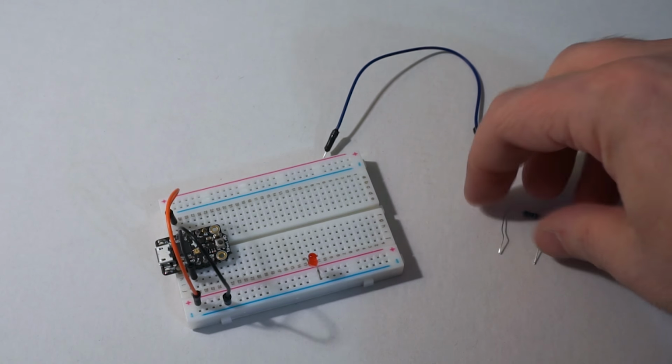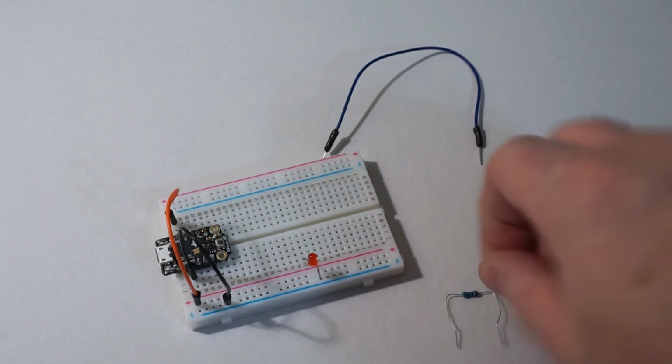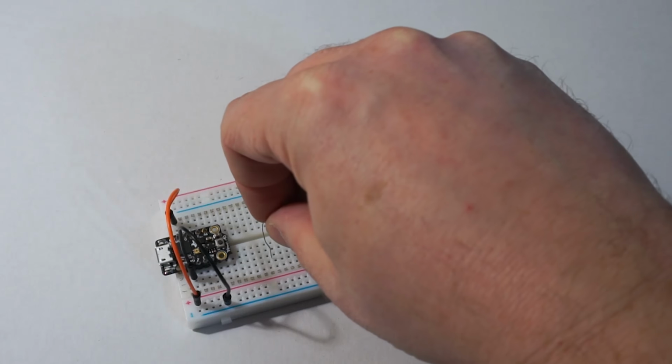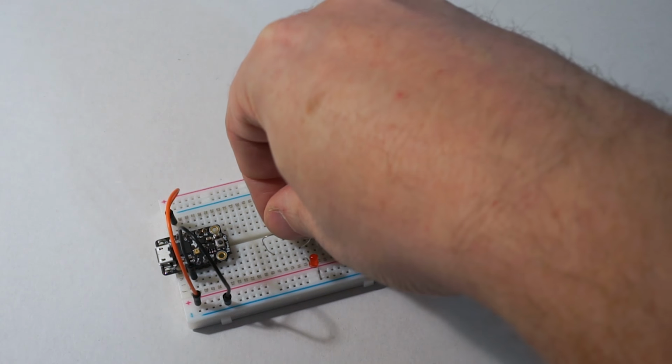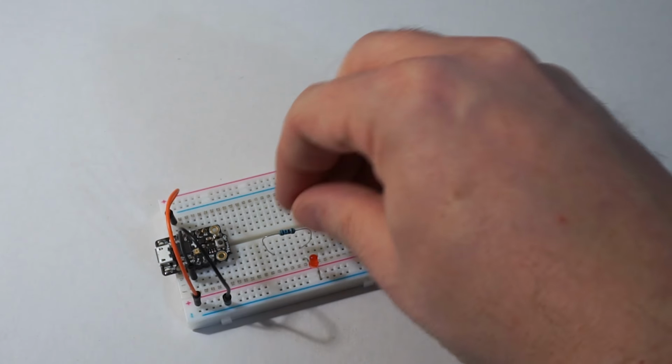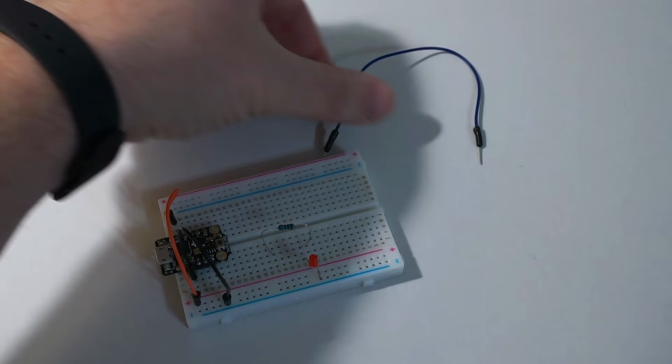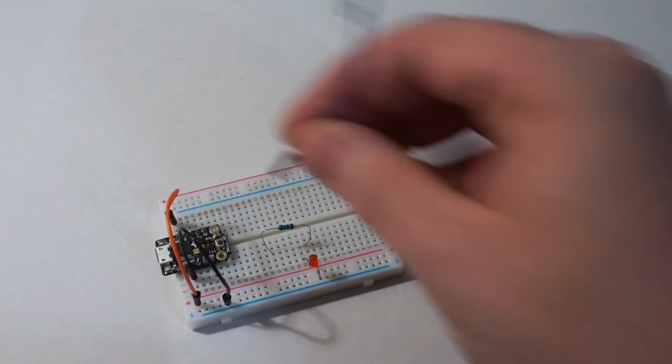And then we're also going to need a resistor, because if you power it up directly, it's just going to blow the LED. So we're just going to put that across 2 connections here. It doesn't matter which 2, as long as it's obviously not connected to something here from the board. Obviously one leg of the resistor needs to go to the same line as the positive leg of the LED. And then the final thing we do is that we take pin number 2.